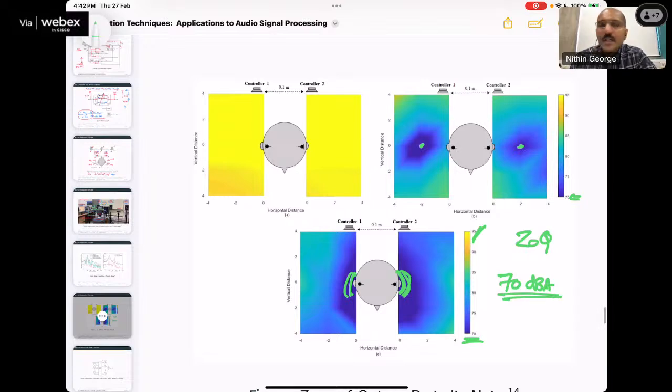So these are sound measures. This is not what you see in the convergence characteristic, not that. Because this is measured using a sound level meter. Sound level meter will give me a dB output. When they say this much decibel sound is there, it's the same thing. Okay, so we had an initial state of 90 dBA for these points in the yellow color. Then after the noise cancellation is achieved, it goes to 70 dBA.